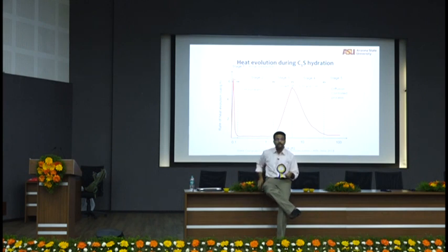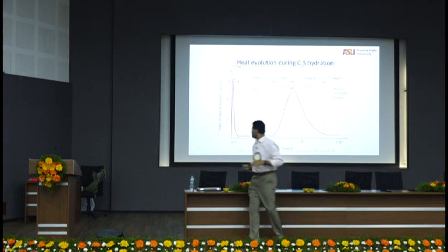Wicking is through a pressure gradient. Okay? All of these mechanisms happen within a cement paste. If you actually look through different hydrating cement paste with boundaries, you can see even pressure differences, osmosis. Even osmosis happens inside the systems. All of you know osmosis, right? Through a membrane potential, concentration gradient. All of these happen within these systems.